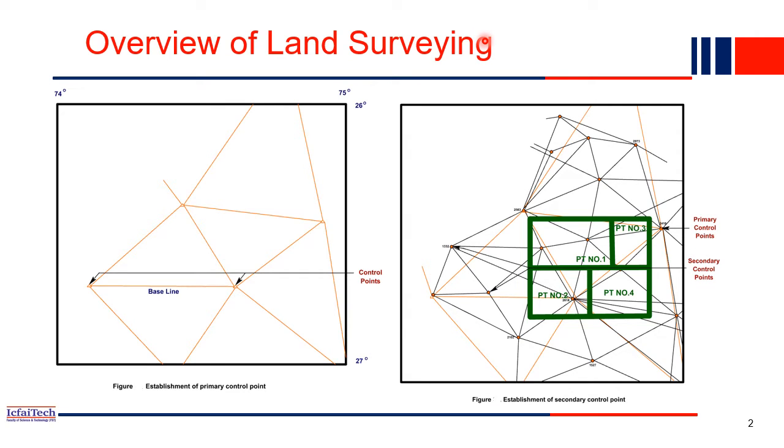Now the data required for making such maps is collected from the field surveying, right? For example, there may be a hill. We go to the site at this location and find out how much is the length of the hill, or if it is a river, what is the width of the river, from where it is starting, where it is taking the turn. All these things we note down, we measure when we go to the real site, and then ultimately we draw it here. So we collect the data required for constructing this map through field surveying.